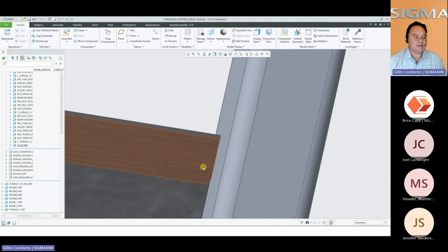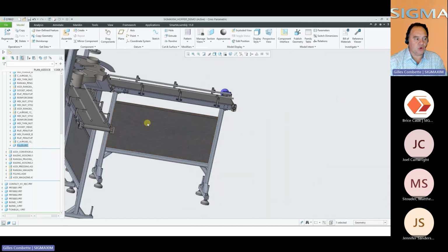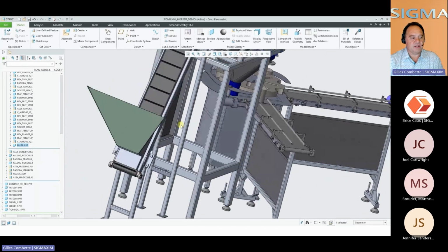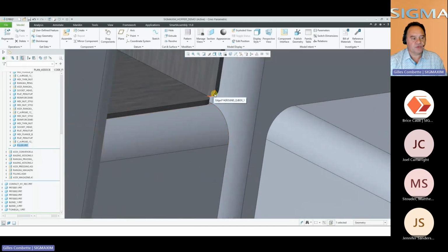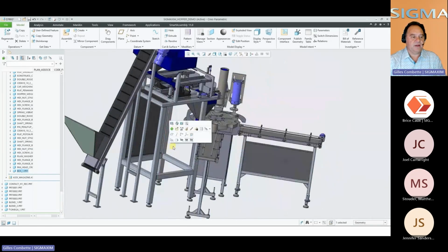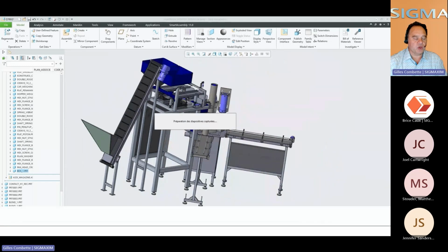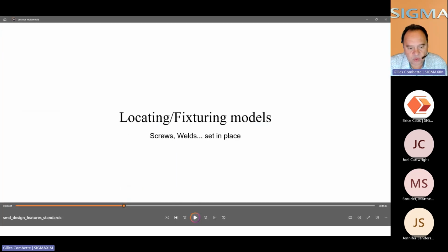The bottom line here is that the main keyword is that this thing is standard to your company. You're using a tool that is a quarter of an inch. You're using a tool that is a radius of 2 millimeters. You're using a tool that is whatever other unit. You define your own setups, and then your user will use it because it's easier for them to use it. And you will always use the same values. So it provides consistency from the design to the manufacturing.